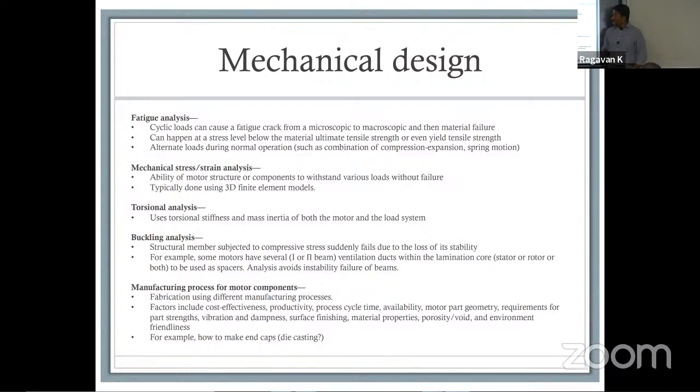And the second one is mechanical stress strain. That basically is the method that allows you to determine the ability to withstand different loads. It also has planned for failure rate. So you have to look at MTBF, mean time between failure. How often or how regularly can a failure happen? Oftentimes you use methods like 3D analysis, 3D FEA for defining the stress analysis.